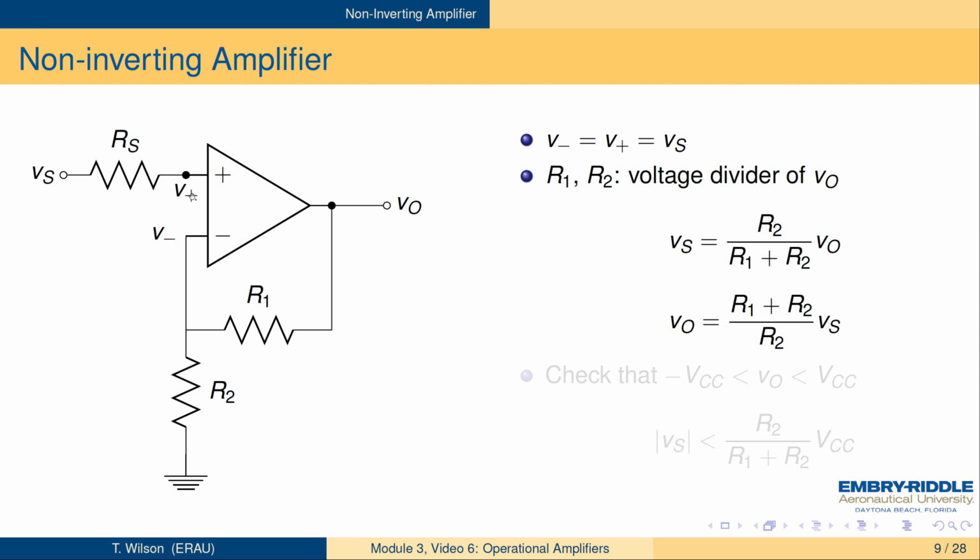So you see what happens. Okay, let's say we've got a V plus here. Say V plus gets bigger. V plus gets bigger, then that's going to make the difference between V plus and V minus bigger. That makes V out bigger. That makes the voltage divider voltage bigger until it gets to be the same. So, I mean, it's a feedback kind of system here.